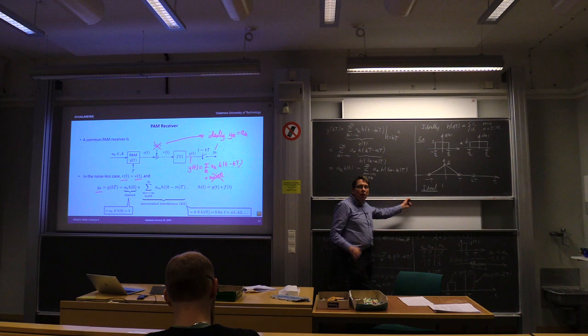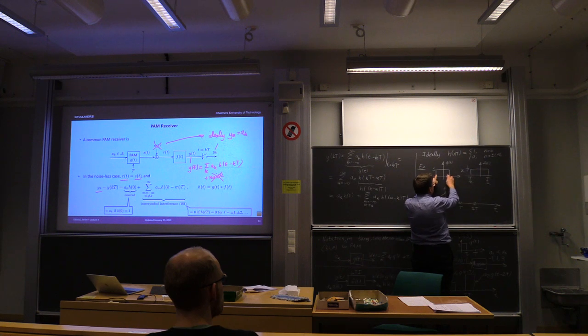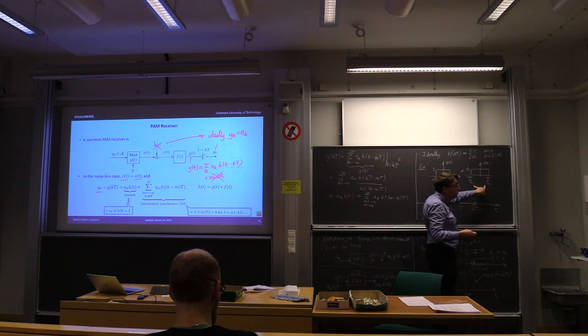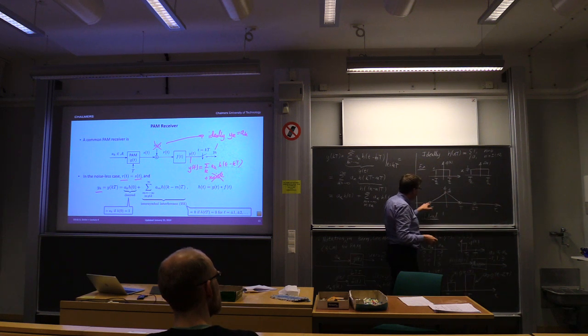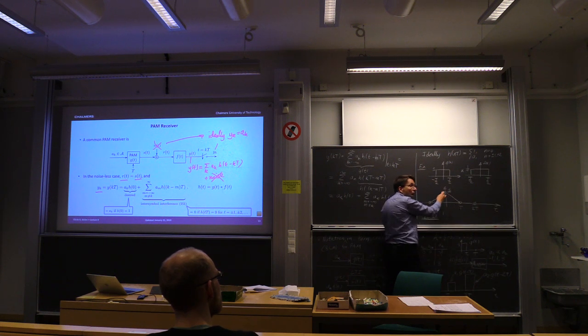Okay. One can show, and it's not hard to show, that as long as the pulse that we're using is confined to a duration of T seconds, where T is the time between pulses, and the receiver filter is likewise also limited to duration T seconds, then we will get 0 points like this, and we will get some amplitude here.